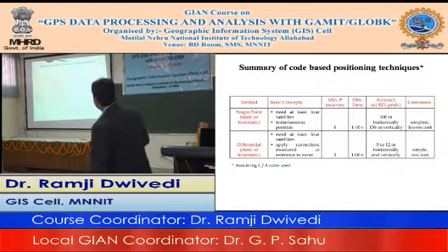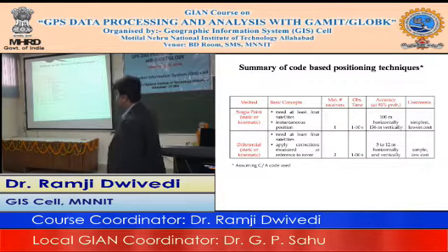Just a term to understand that it is one of the lowest cost single point positioning. And you have a differential, so you could see the improvement in terms of horizontal and vertical, and you need at least 4 satellites. So a common satellite would be there, so that the correction could be applied in a proper sense. Apply corrections measured at the receiver reference to the rover.